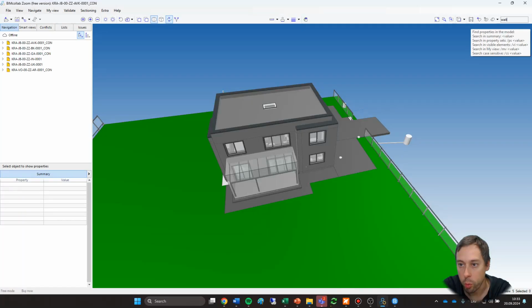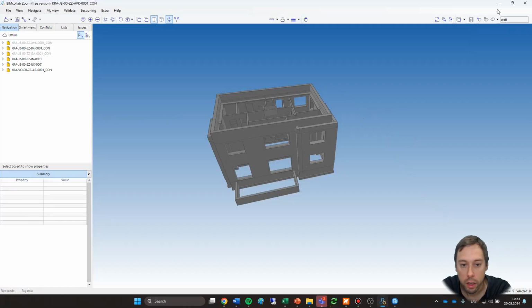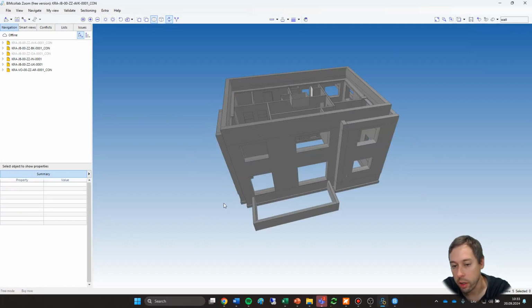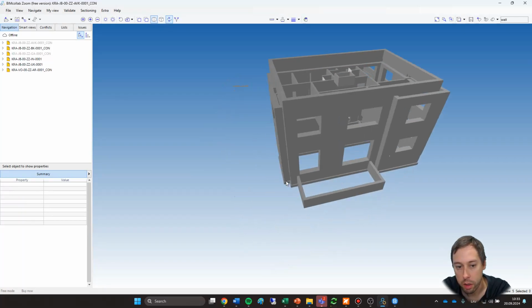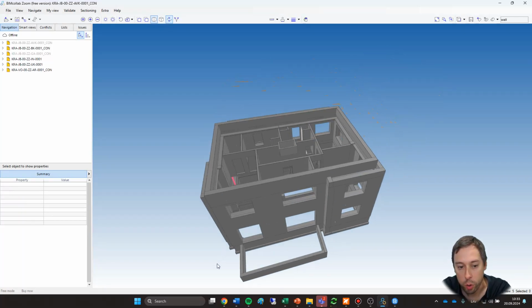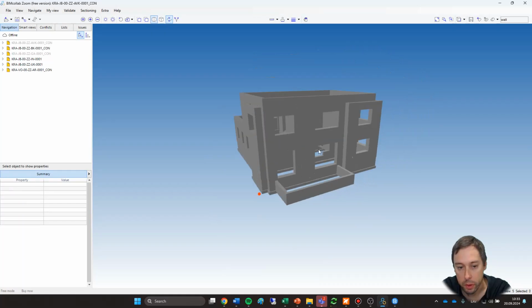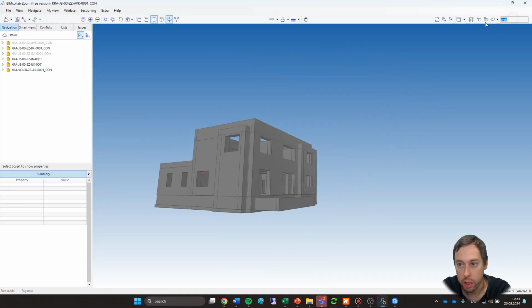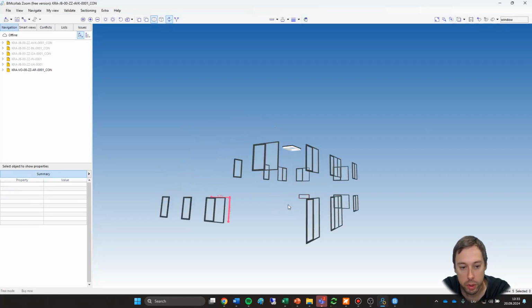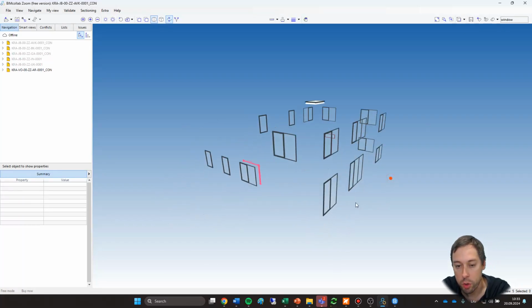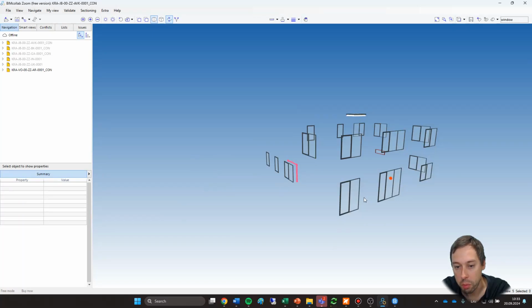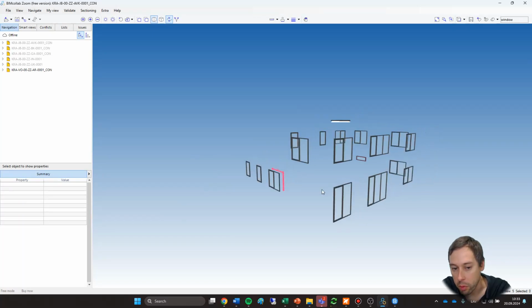Let's say I'm going to write wall, and here it shows all the elements that have a parameter called wall inside. So I can use any function, but this also depends on how the objects are made. If a wall is made with some other tool, which is possible, then this might not work properly.